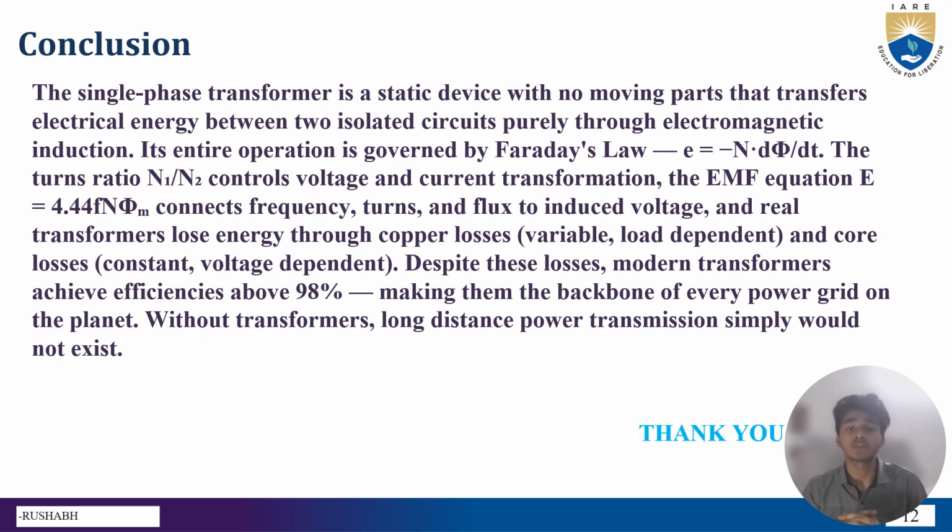The EMF equation E is equal to 4.44 into F into N into phi m connects frequency, turns and flux to induce voltage, and real transformers lose energy through copper losses, variable and load dependent, and core losses, constant and voltage dependent. Despite these losses, modern transformers achieve efficiency above 98%, making them the backbone of every power grid on the planet. Without transformers, long-distance power transmission simply would not exist.